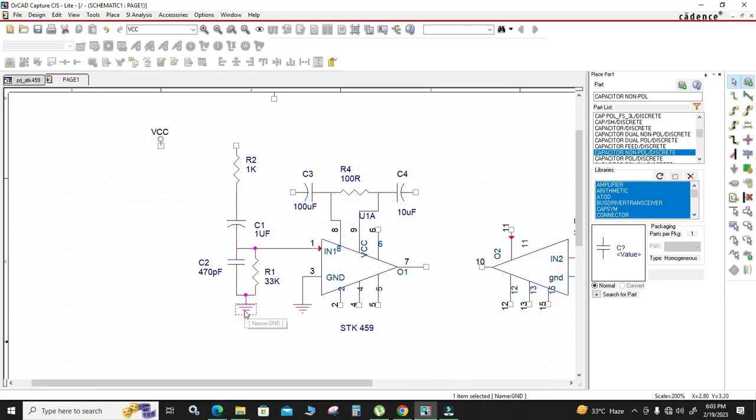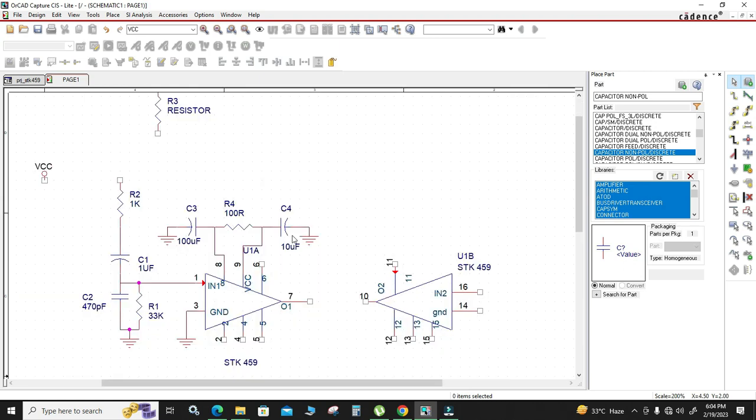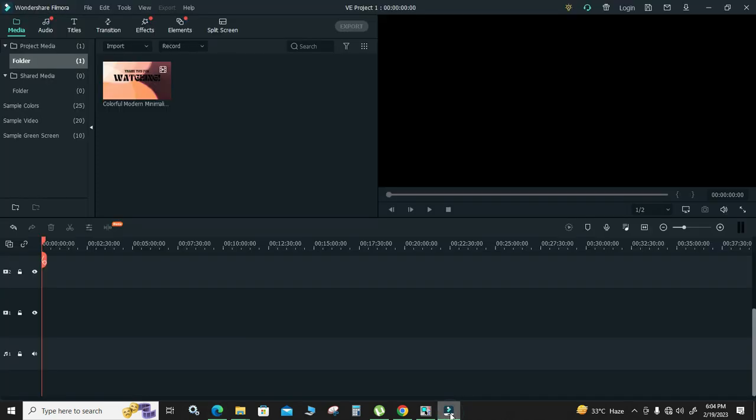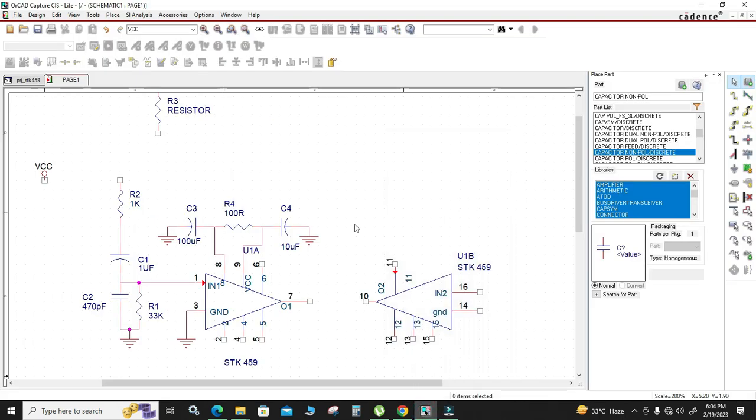Click, control and copy these grounds again. Connect it. Click and drag. Control and drag. Copy again. Connected. Yeah. Yes. Okay. Then you should notice here is a VCC connected directly to the 9th pin. So we have to connect that VCC here. So check here, this is the 9th pin. The 9th pin is directly connected using wires. Right, the 9 VCC here.